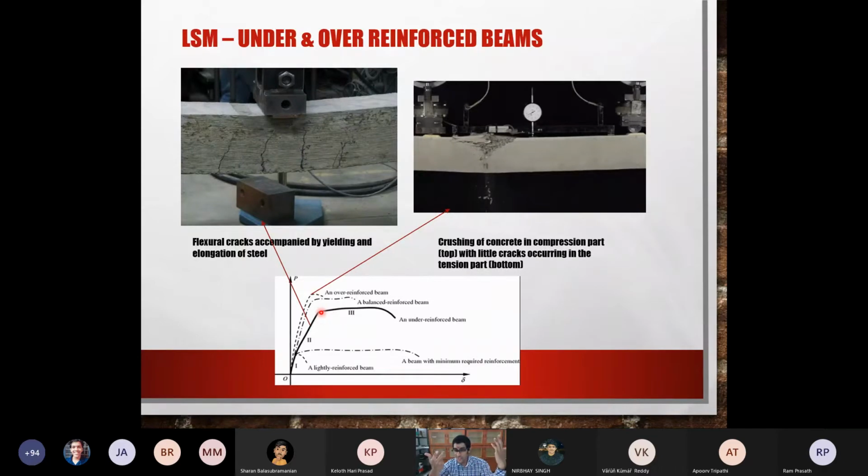So when you do not have any reinforcement, what will happen to the tension part? Immediately when you load it, even if it is M25 concrete, once the tension exceeds 5 Newton per millimeter square stress, the concrete will fail. That is the reason why there is such a big difference.